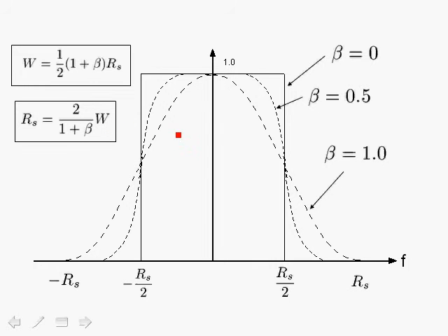This is very interesting. This shows that by controlling the roll-off factor, and thereby controlling the amount of excess bandwidth, as you can see over here, we can actually improve the throughput through the channel. So the maximum throughput through the channel is achieved with beta equals to 0. And if we use beta equals to 1, then we get half the maximum throughput. So there's a basic trade-off between having a filter which is broader in the frequency domain and therefore time limited, which is what we need, and at the same time the throughput of the system.